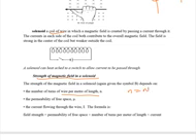Then the permeability of free space, and the current flowing through the wire. Combining all this, the field strength is the product of these three: the permeability of free space, the number of turns per unit length, times what? The current. Therefore, you can use this equation to calculate the field strength in a solenoid, but small n is the number of turns per meter.